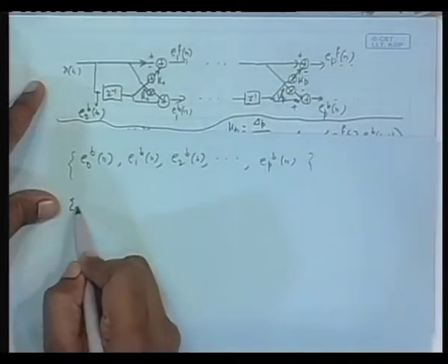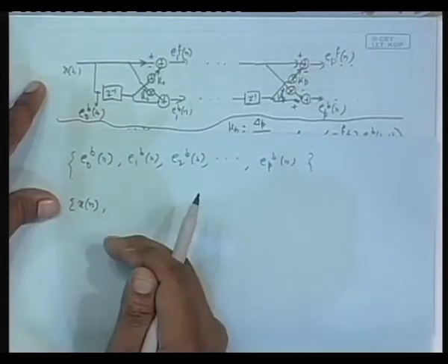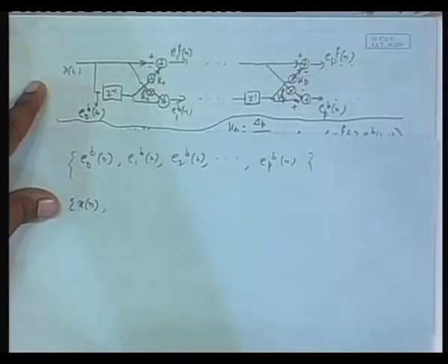Suppose I have got this space Xn. After all, if I want to do say Wiener optimal filter, we have done LMS algorithm and before that optimal filter, what we are doing then? We constructed a pth order filter. That was what? Projecting orthogonally Dn on the space spanned by xn, xn minus 1 dot dot dot up to xn minus p. This is projecting orthogonally, that projection coefficients were the filter coefficients that we have seen.